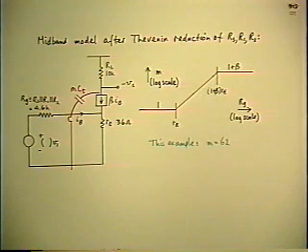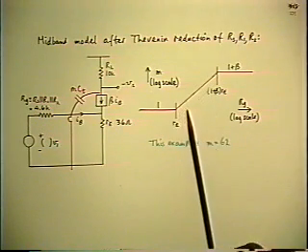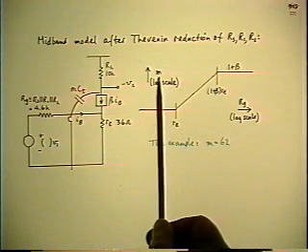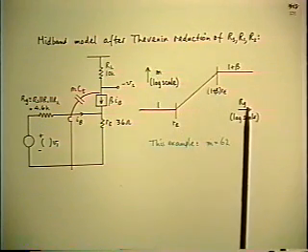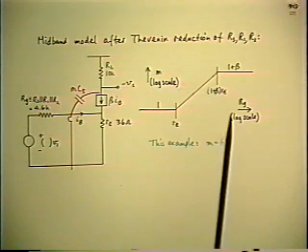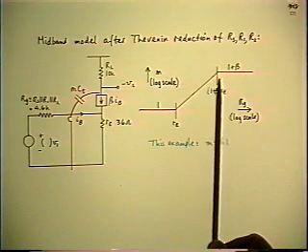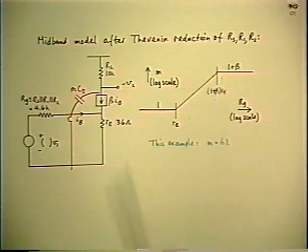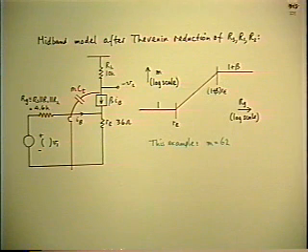One refinement about it also. These represent asymptotes, of course, and the actual function, M as a function of Rg, has smooth corners, just like the frequency response really does. In frequency response, remember the actual curve is 3 dB away from the asymptote intersection. In this case, the smooth curve is 6 dB away from the asymptote intersection. Why is there a difference?